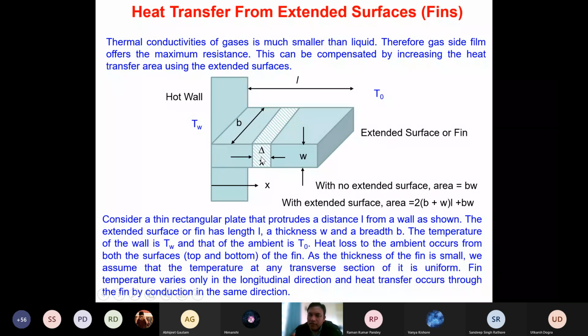Correct. Now, in addition to rate of heat input to this shell and heat output from the shell, again from this surface which is outside here, isn't it? There is a heat dissipation taking place to the ambient, isn't it? And what will be the area for the heat dissipation here? What will be the area? All these areas surrounded here, isn't it? Do you all agree? Yes, sir. So that will be what? That will be 2B,